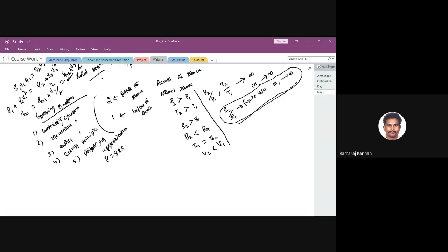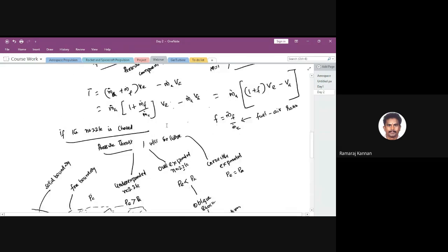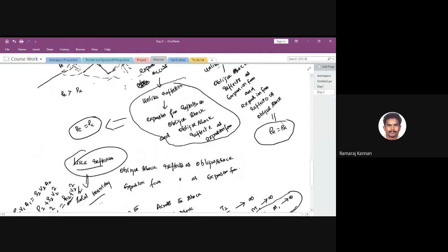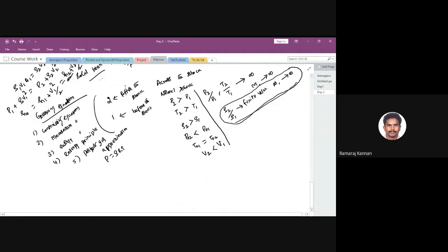From the examination point of view, these things are going to be given much priority. Because I started on compressible flow, I went into it, but anyway, keep that in mind. One difference between your normal shock and oblique shock is that, except for the velocity, the remaining things are going to be the same, but the increase in static pressure is going to be smaller.